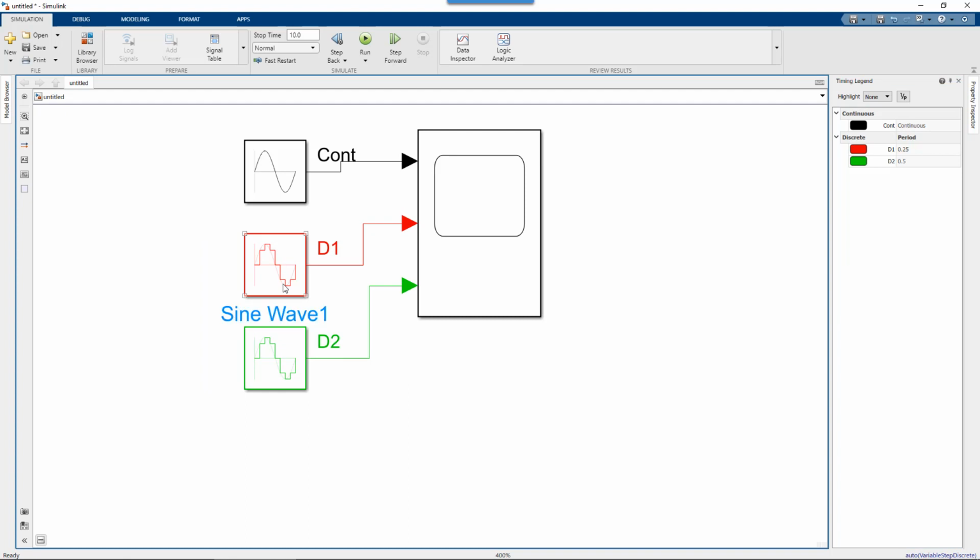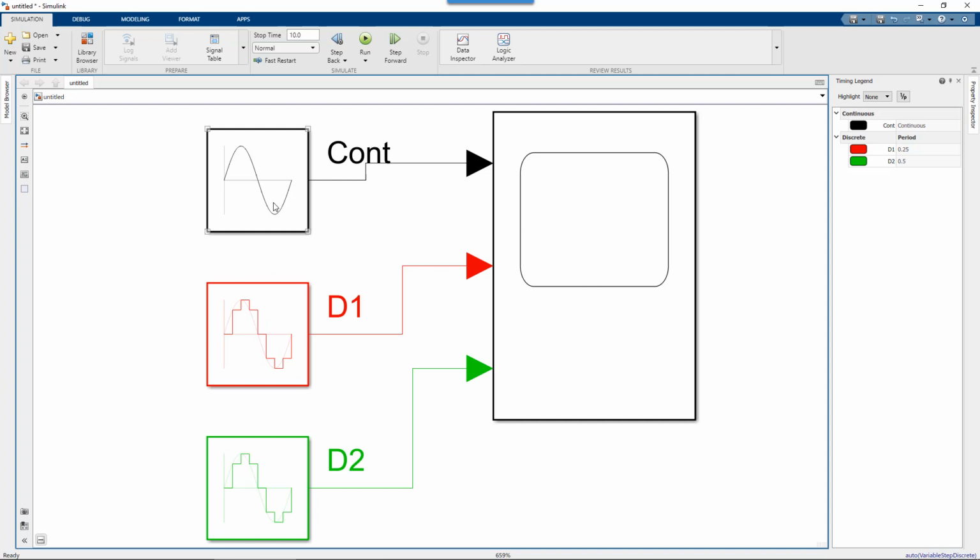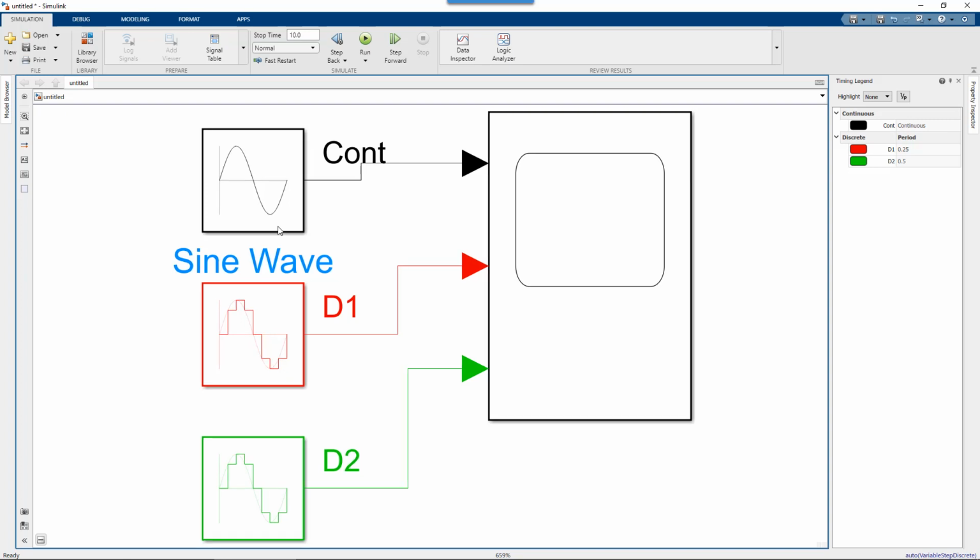This gets really relevant if you ever start getting into advanced systems where you have different parts of your algorithm running at different rates, or if you're using systems on a chip, especially if you're just putting something on an FPGA, something on a processor. This starts becoming very important. If you're just doing schoolwork, if you're a student, there's a much higher likelihood that you can get away just leaving everything in the continuous time domain. But if you're taking a controls course, they may ask you to intentionally go to the discrete time domain, the Z domain, for those reasons.